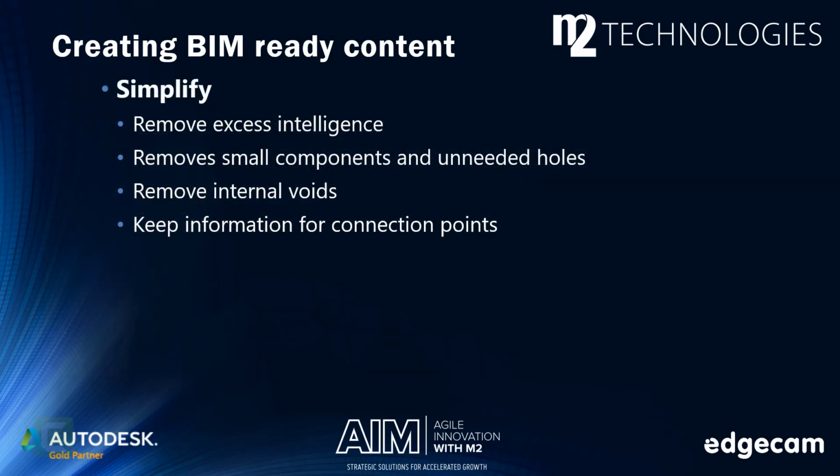So getting your model ready for BIM consumers, right? Creating BIM-ready content, you first need to simplify the geometry. BIM consumers don't want high detail. Much of the stuff that we have is unnecessary and doesn't fit. Internal components are generally the number 1 piece, right? We don't need to let them know what we have inside.